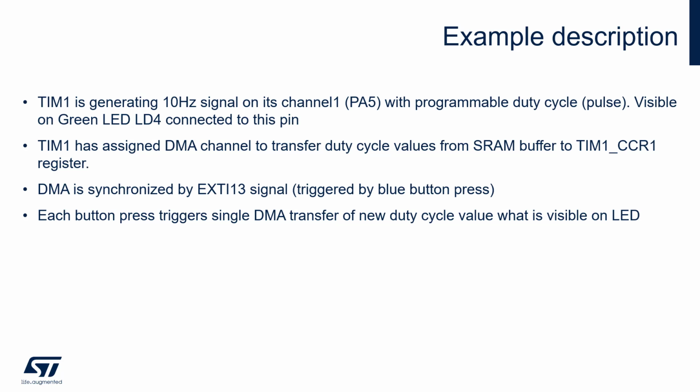Timer 1 will have an assigned DMA channel to transfer its duty cycle, so-called pulse values, from the internal SRAM buffer to timer 1 capture compare register 1. And DMA will be synchronized by the external interrupt EXTI13 signal triggered by the blue button press.